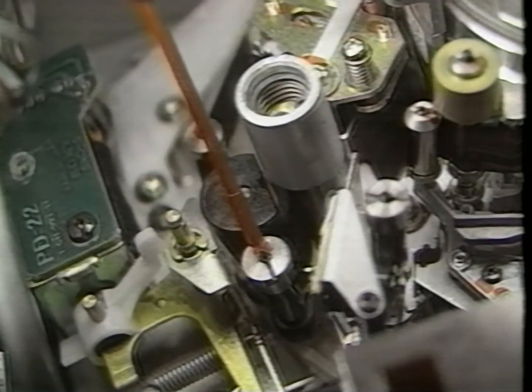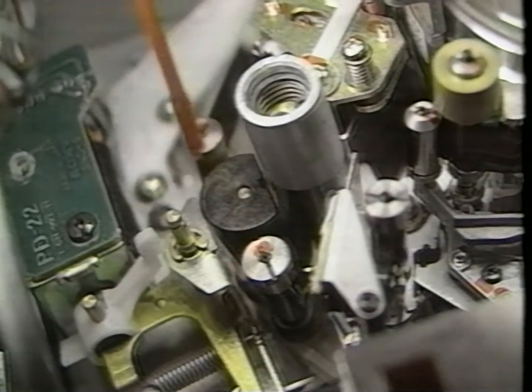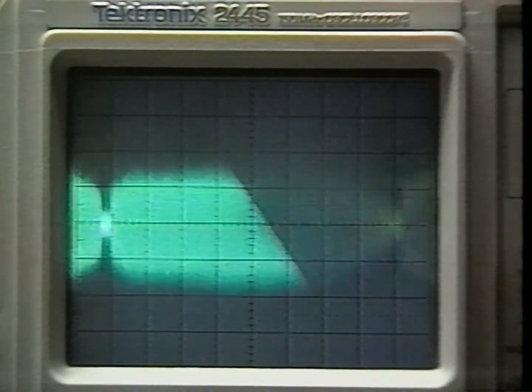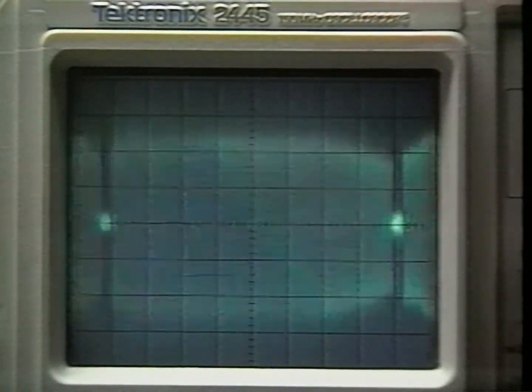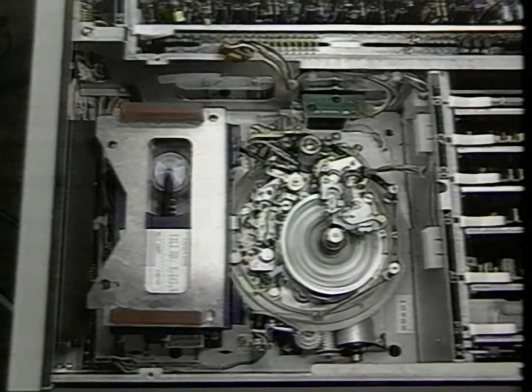In addition, the leading guide roller on the threading ring should be adjusted so that the tape contacts the upper flange. As a final check, the tracking knob should be turned slightly back and forth and the waveform should remain flat. In addition, all guides should be locked down and checked for tape curl.